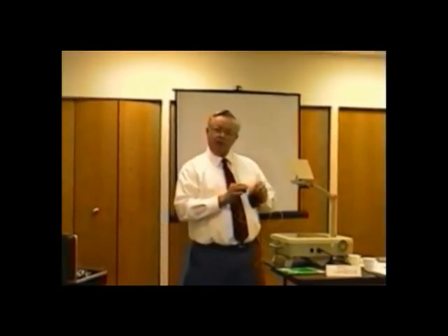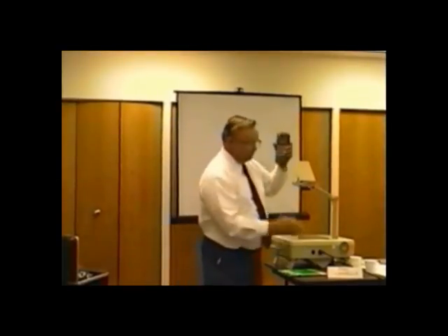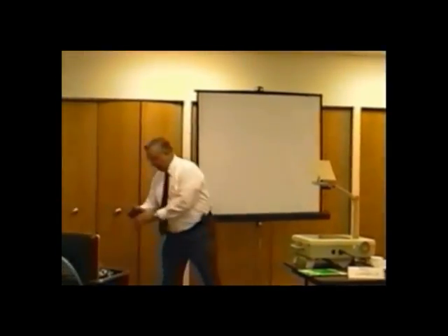But we're going to tell you that you can take a thermocouple and put it on your suction line and tape it. Take a piece of tape and tape it, and then take a piece of insulation, cloth, paper, anything. Insulate it and tape that so it doesn't come off. If we're going to be measuring suction line temperature, the sun is beating on it, we do not want to influence this by the sun. So on the suction line, tape it, insulate it, all right? Then at the same time, you can take another one or the same one and take a couple of readings and put this on the bottom of the condenser, on the liquid line, okay? You can put both of these, ladies and gentlemen, right close to your service valves, because the high side service valve is on the bottom of the condenser.